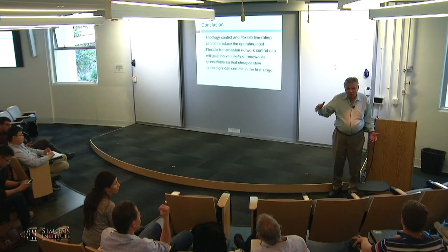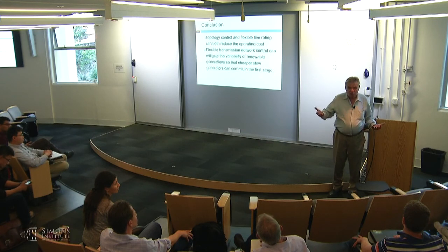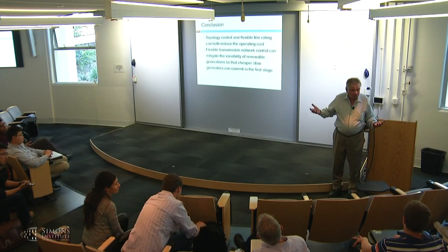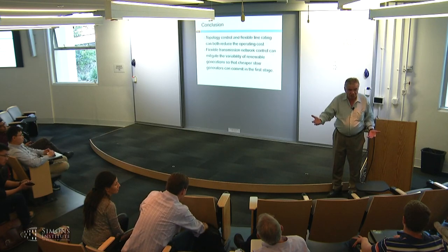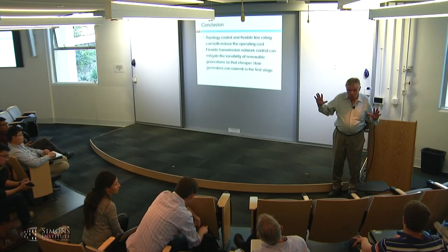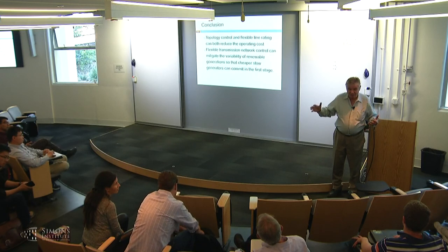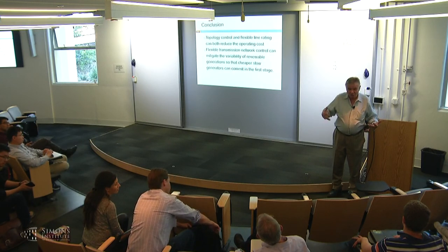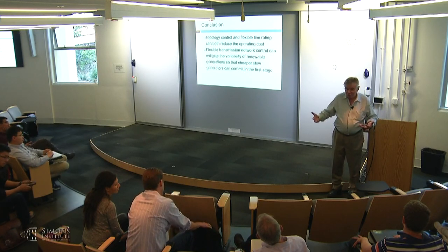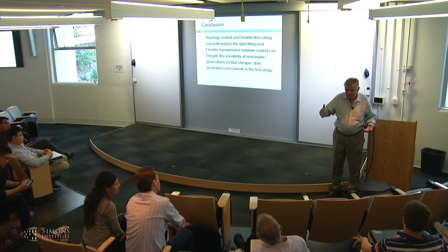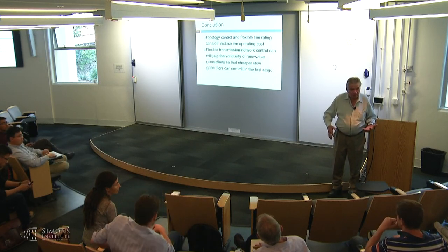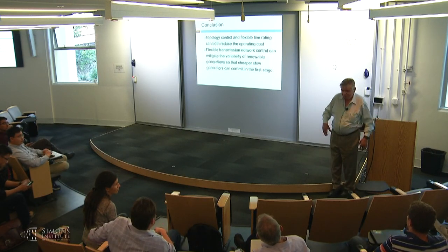In the old days, they used to build transmission just for reliability. Now we're building transmission for economics. We're building redundancy in the transmission lines using economic criteria, not just reliability. So if you are going to build transmission for economics, you should be able to consider disconnecting lines for economics. And that's what we're doing.